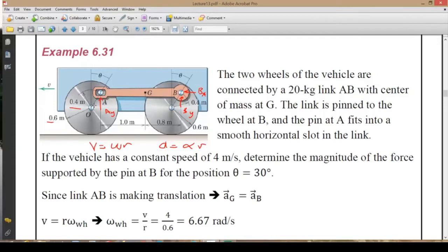And as a result of that, it has the same link length, so it kind of looks like this 4-bar mechanism that we have discussed in the beginning of our kinematics lecture. If you remember that, you will also remember this coupler link's motion is a curvilinear motion. That means it does not rotate. The only type of motion it's going to have will be a translational motion, and it's a curvilinear translation.